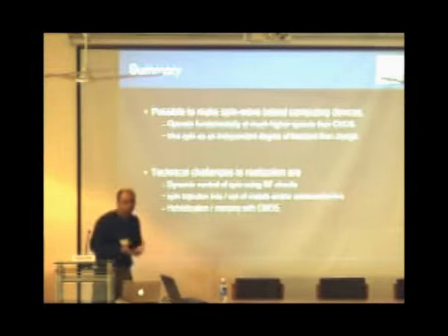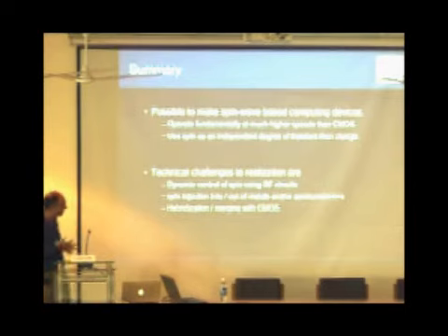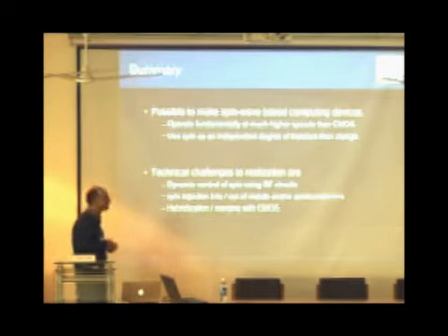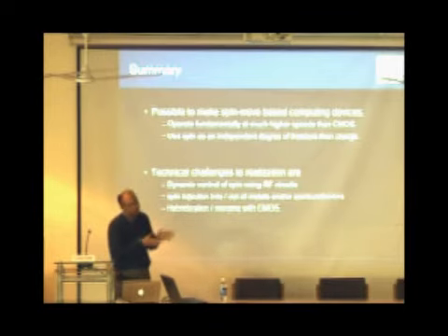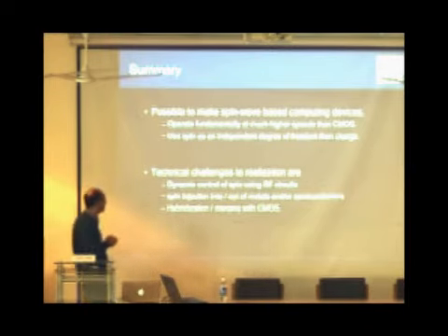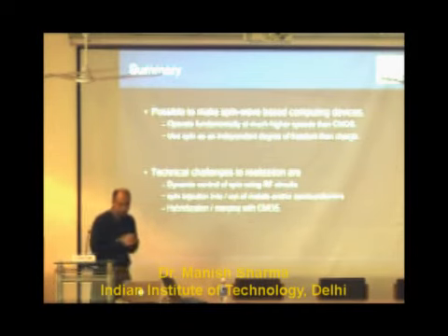It is possible to make spin wave based computing devices, but there are some real serious issues. You have to work at RF frequencies, and you have to learn how to do RF design and control of spins independent of the semiconductor part. But the good thing is you are working mostly with metallic systems, especially ones which have been very well understood by the magnetics industry, and most of the processing is compatible with semiconductor CMOS. So in the future you could take some of these devices and connect them with CMOS circuitry if you wanted, on the same wafer. So that sort of merging with CMOS is quite possible.